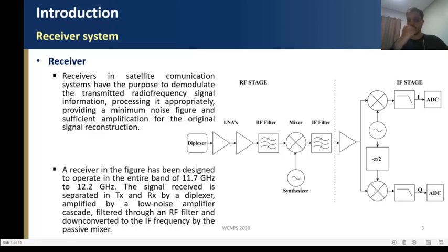The heterodyne converter was defined in two stages, converting the RF signal from 11.95 GHz to around 3 GHz. The transceiver then down-converts the frequency to baseband.